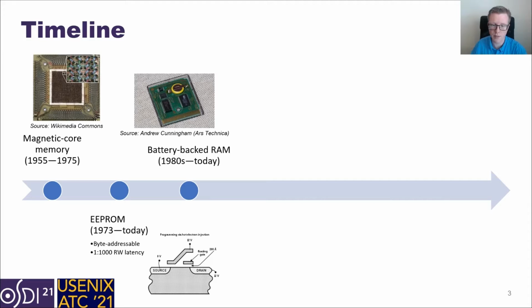The next notable persistent memory devices are battery-backed RAM technologies. These memories could retain data for years, like in the case of battery-backed SRAM contained in Game Boy cartridges. Unfortunately, large capacity devices typically draw more power than your typical coin batteries can supply for long, and so these memories are not a good solution for storing larger volumes of data. During this time period, we do see academic research on persistent memory systems, for example, on programming language abstractions, where persistent memory operations would be transformed into database transactions. However, these systems never saw serious adoption, as persistent memory programming wasn't practical from an efficiency standpoint.